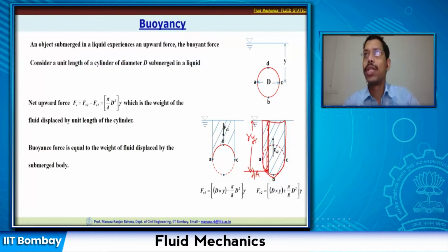So now this strip, what we have shown, is basically exerting the pressure in the upward direction. So instead of showing it outside like this and integrating, I am just showing it for quick understanding that this weight of water or this volume of water is exerting the force on this surface, but that is acting upward.